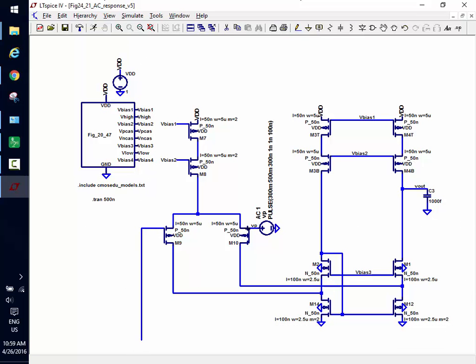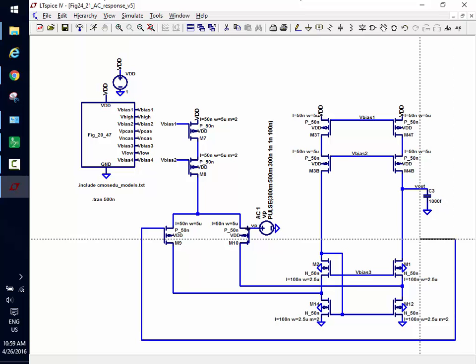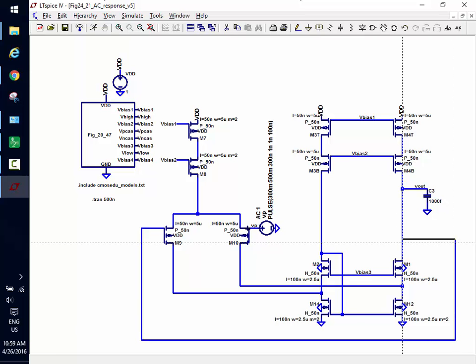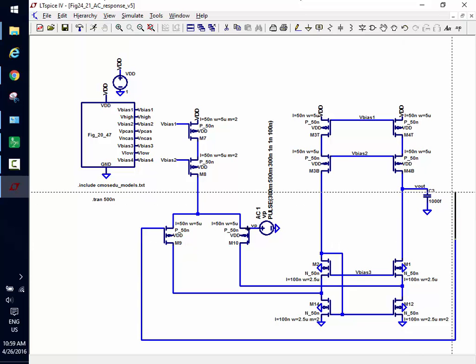Notice if we did this with a diff amp in the 50 nanometer process, it wouldn't be that good because the diff amp has low gain for 50 nanometer, but we're doing folded cascode, so it should be pretty tight. The output should follow the input pretty well. Okay, any questions on what I did there? Does everybody follow the flow of water? You got 20 flowing here, 10, 10, 20 in these, and then I've got these as constant current sources.